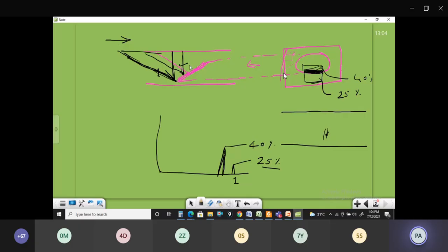Similarly, when it comes to point number 1, 2, 3, 3 will come further here. Then point number 4 will come further here, and then point number 5 will come further here. So like that, it has taken some 4, 5 points, and each point has been separated at some distance. And at every location, we know that depth is different. So that is how it is able to give me this. Now, this thing is approximately matching with this orientation. So that is what we mean: in the B scan, we are able to see the orientation.